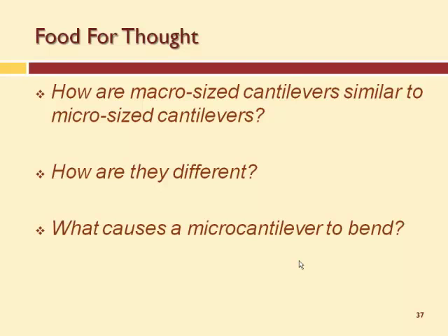So when they make atomic force microscope tips, they have ways, using etching of crystals, to make a perfect step. Perfectly vertical. So they know that this is perfect. And then they drag their tip across and they see how sharp this edge is. So if it's very sharp, then they know they have a good tip, and if it's not so sharp, it has a defect in it, they know they don't have a good tip.